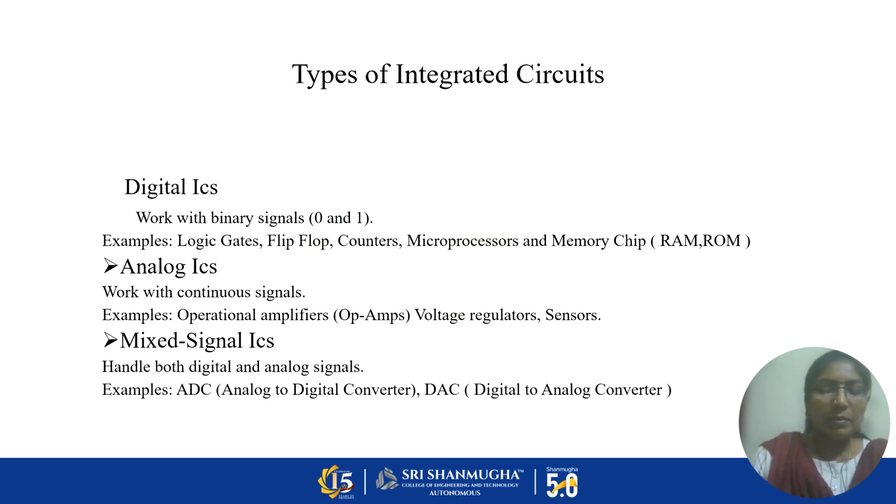To overcome these limitations, the sequential circuit was developed. So what is a sequential circuit? It is a digital logic circuit whose result depends on the present and previous input, meaning it has memory. Examples are flip-flops, counters and registers. Sequential circuits store information, use flip-flops and latches as memory, and the output changes based on clock signals. Sequential circuits are built with flip-flops and combinational circuits are built with logic gates.